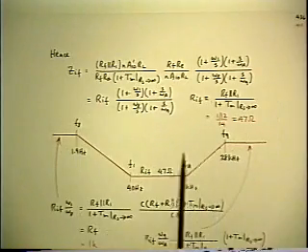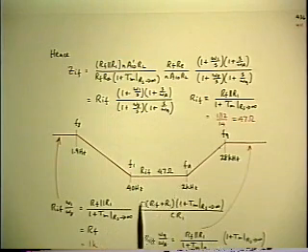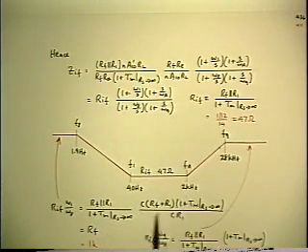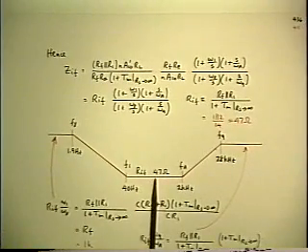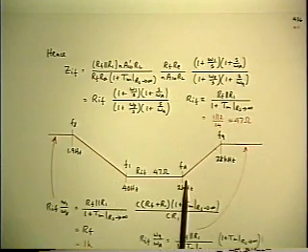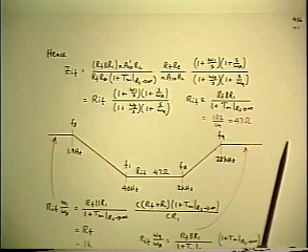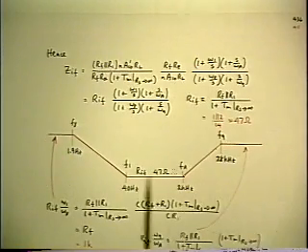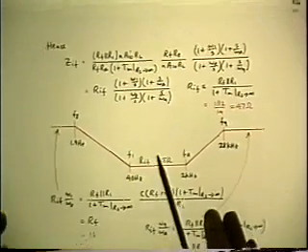So I won't bother with the details, but this is the result. It's a mid-band value, which is low, as expected because it's shunt feedback. And it rises outside the range where the loop gain starts to go away, and it does level off at both ends. So it's got 2 poles and 2 zeros, and it's a more complicated result than the output impedance was.